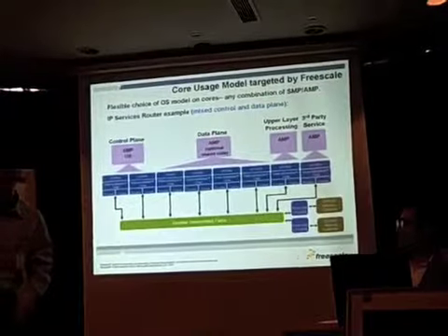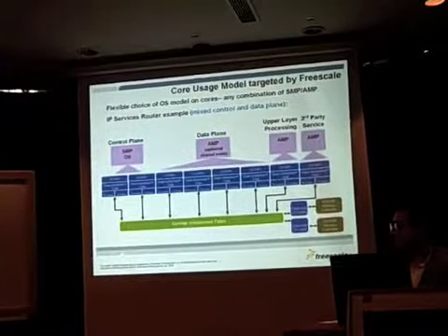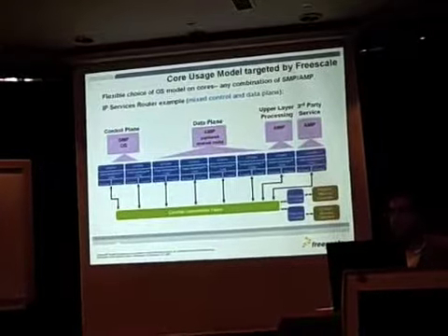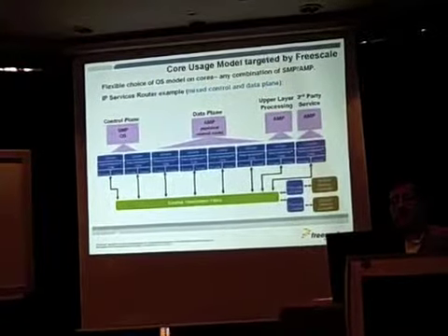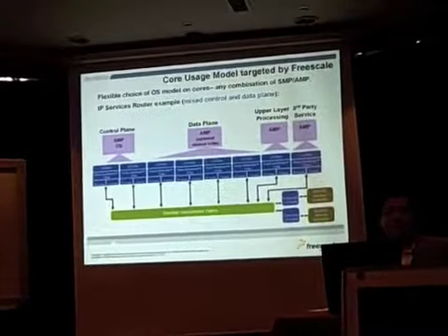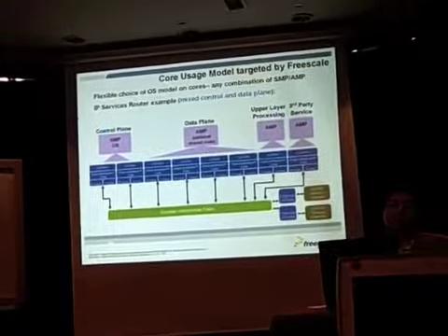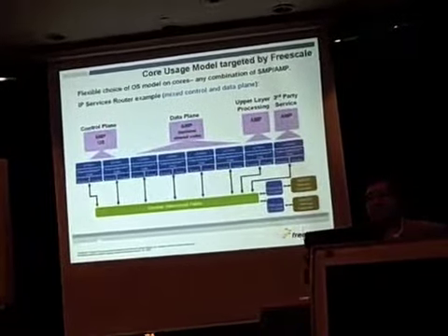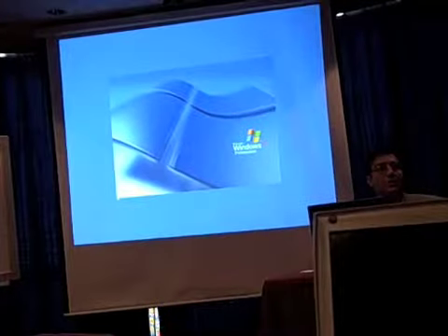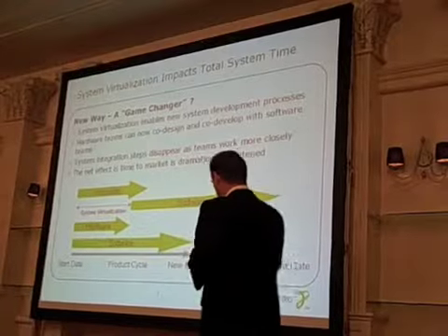Yeah, so synchronization and scoreboarding is a really important task and topic area in multi-core, based on what you're saying. And it's the same concept. Power Architecture was one of the first architectures that brought the notion of superscalar architecture to microprocessor design. We introduced out-of-order execution, but that same thing that we did at the micro-architecture level is now needed at the macro-architecture level, where you have to keep track of the tasks. Let me explain.